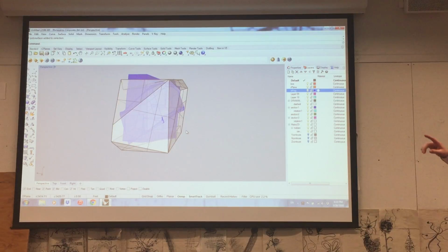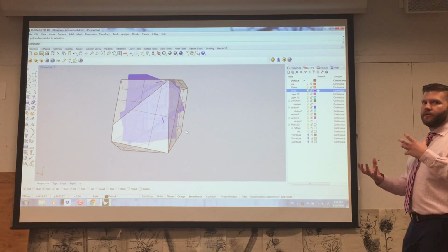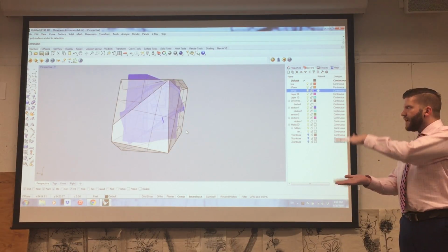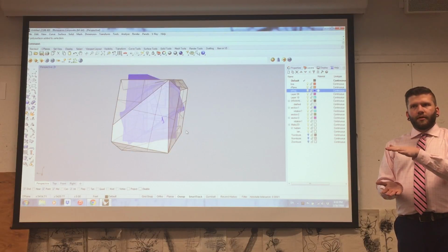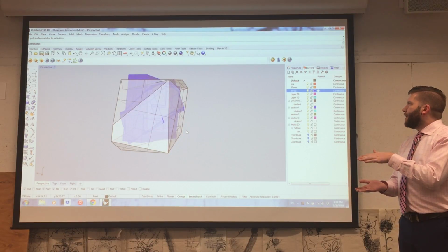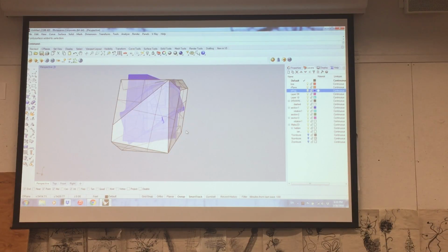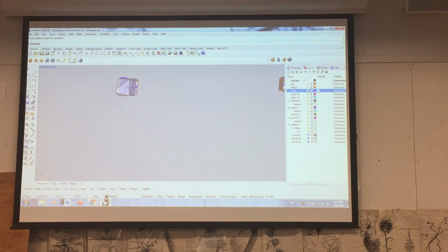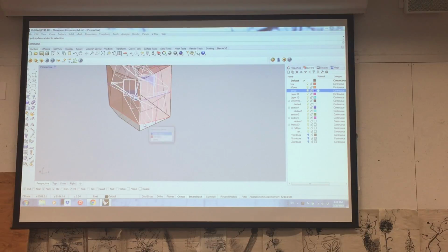However, if you do, you should scale down the interior first by a little bit, 4%, 5%, something really small. So that the only part of the interior that's coming outside are those faces that you mirrored, okay? And what I need to do is bring this box back since I deleted it.